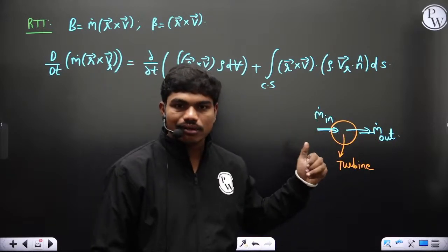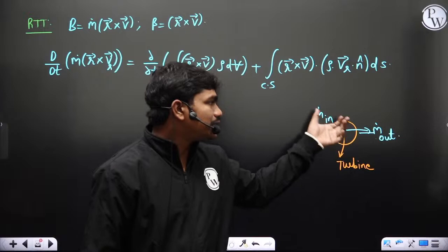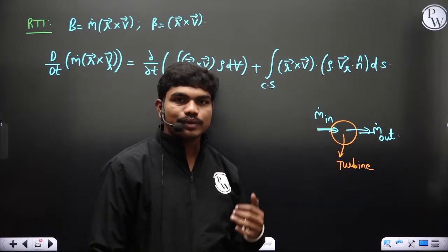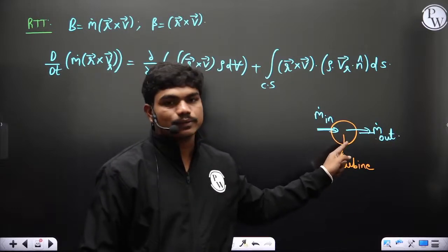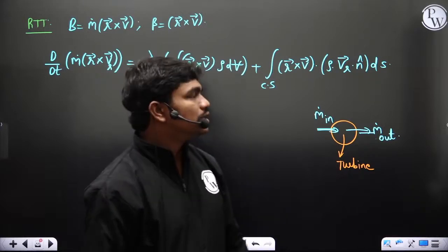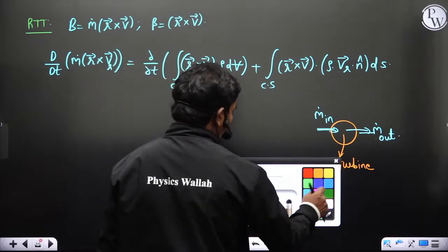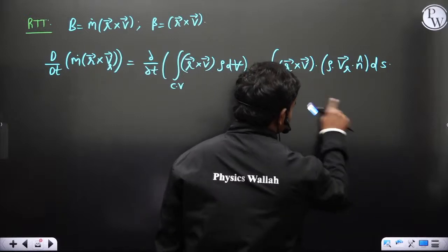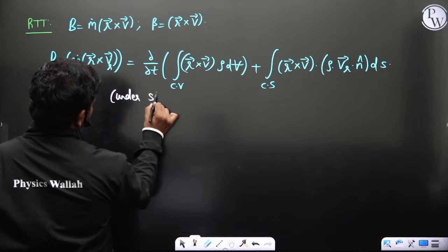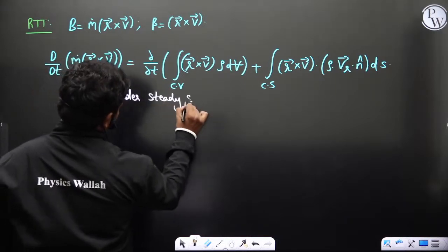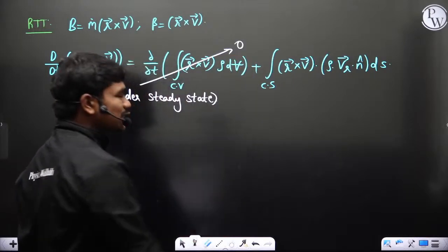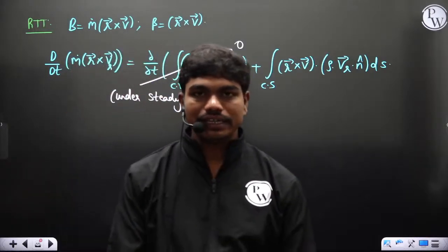And similarly in terms of energy, right now here we are doing only the adiabatic case, but even if there is some heat transfer, there should be an energy balance, otherwise the temperature of this device keeps on increasing and very soon it will reach the metallurgical limit and the material will fail. So because of these reasons, the devices have to operate under steady state. So under steady state, clearly this quantity is 0, since it's a partial derivative with respect to time.